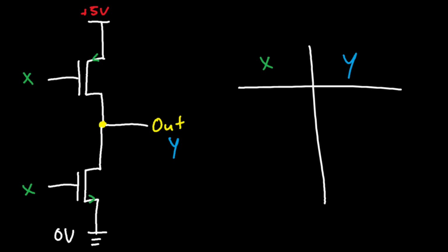New example, let's take a look at this gate, or this circuit. Looks a little more simple. There's only one input X. I guess you can already take a guess what this circuit is, but let's look at this. P-type, N-type, right? So this guy right here, let's just mark it down. Maybe it'll help you a little bit. But this is a P-type and this is N-type. So since there's only one input, we only have two possible combinations of inputs, 0 and 1.